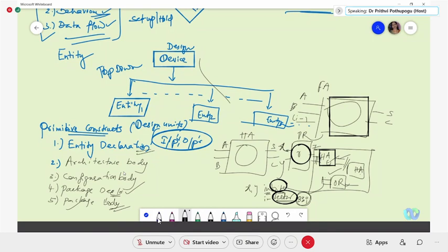So, by default, all these 5 elements will be there when you are writing the HDL program. You will be having the entity or module declaration, and that will be defined by your hardware that is defined in this entity, or your module will be completely bounded or completely defined in the architecture body. And your architecture body defines the hardware.